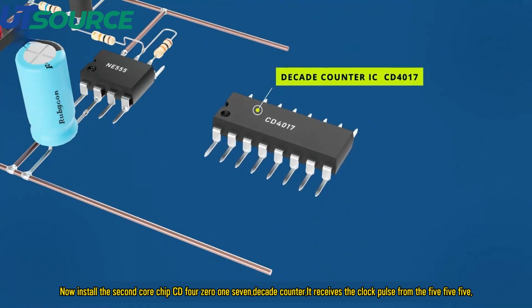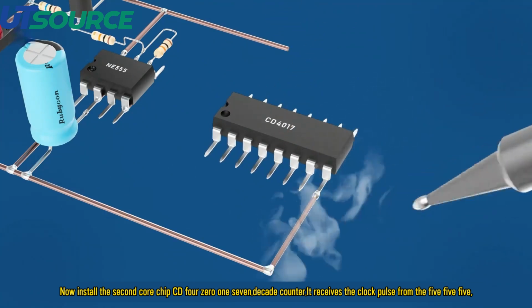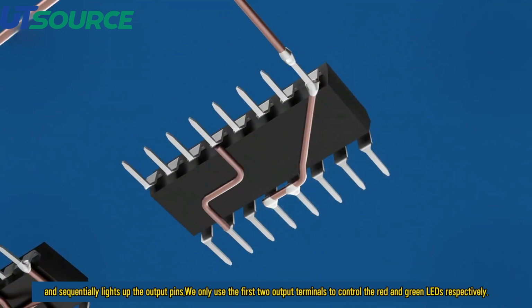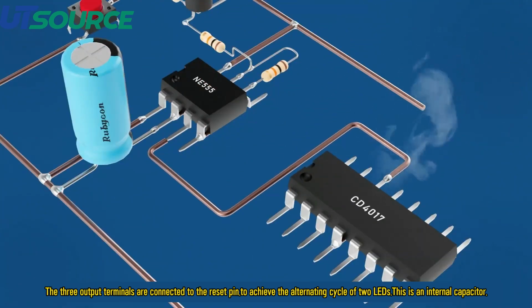Now install the second core chip, the CD4017 decade counter. It receives the clock pulse from the 555 and sequentially lights up the output pins. We only use the first 2 output terminals to control the red and green LEDs respectively. The third output terminal is connected to the reset pin to achieve the alternating cycle of 2 LEDs.